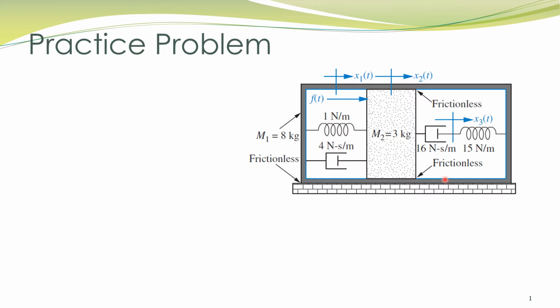We want to have its mathematical model. We shall apply the shortcut that we have studied, that is x1 of s. We are working in the Laplace domain, so everything is in the Laplace domain. x1 of s multiplied by the sum of the impedances which are connected with this displacement.